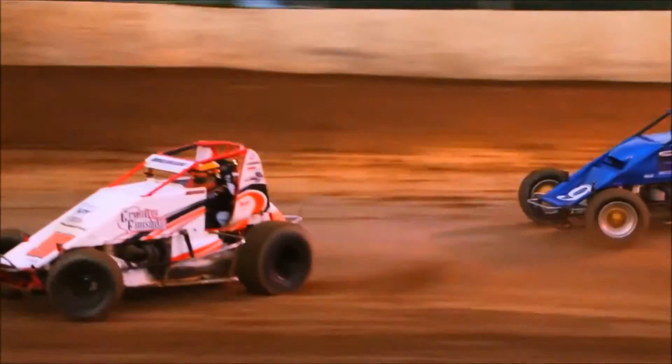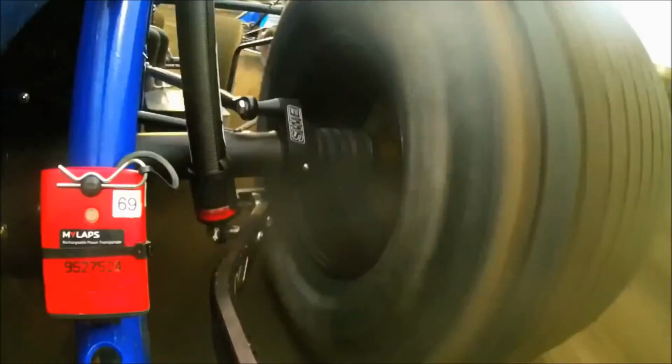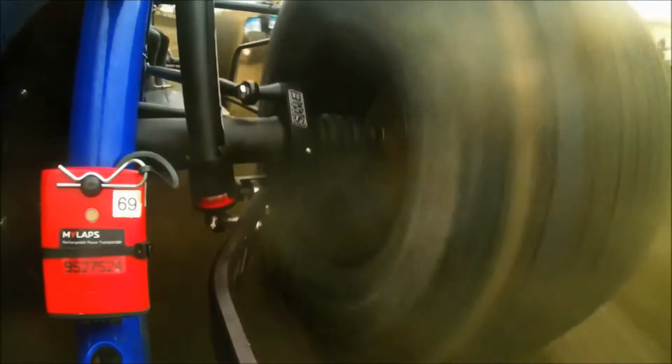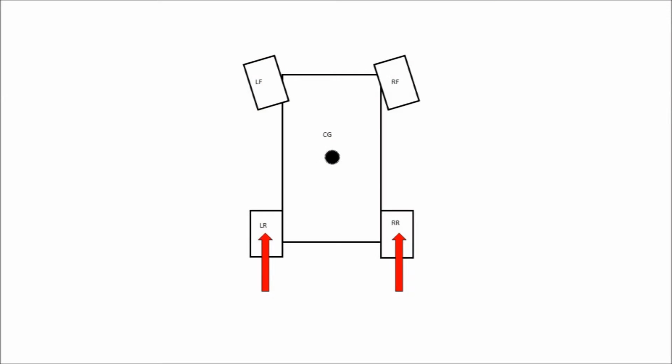The stiffer a tire's spring is, the more weight transferred to that tire in the turn. When doing an analysis for a circle track car that only turns left, for the rear axle, we look at the rear drive force for each tire. When one drive force is larger, this creates a moment around the center of gravity. As seen here, when a larger driving force is on the right rear, a positive moment is created, helping the car turn left more and creating oversteer. The opposite can be observed when more drive force is on the left rear tire.